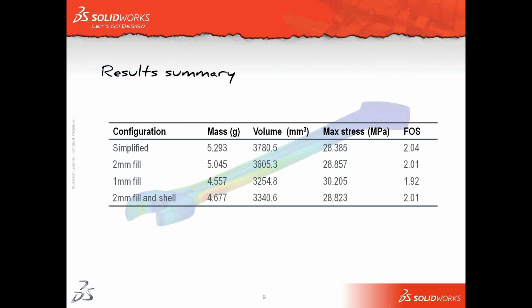So we can see how that mass and those volume values vary with each of the models, and we can see how the maximum stress values increase or decrease with each of the changes that we make. If, say, we were only interested in factors of safety above 2, we can see here obviously that the 1 millimeter fill configuration isn't suitable.